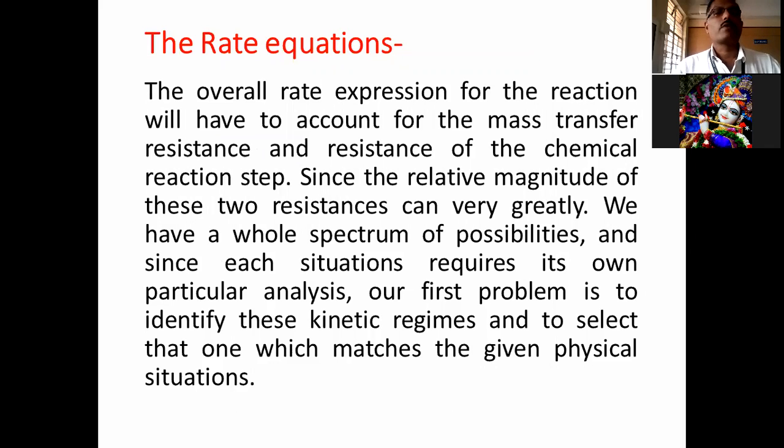Okay, so in the fluid reaction, the overall rate expression for the reaction will have to account for the mass transfer resistance and the resistance of the chemical reaction step. Since the relative magnitude of these two resistances can vary greatly, we have a whole spectrum of possibilities, and since each situation requires its own particular analysis, our first problem is to identify the kinetic region and to select the one which matches the given physical situation.